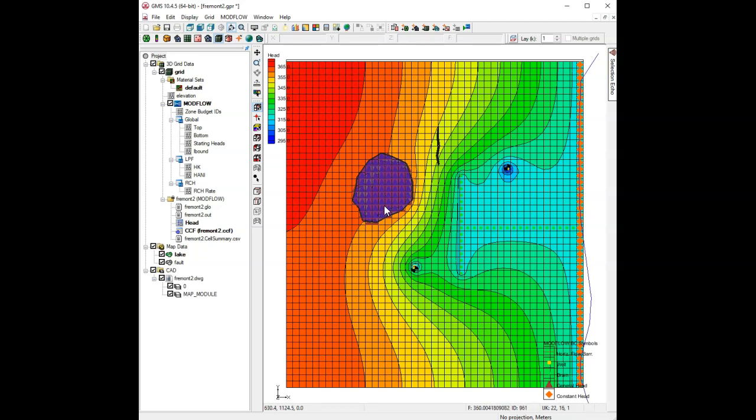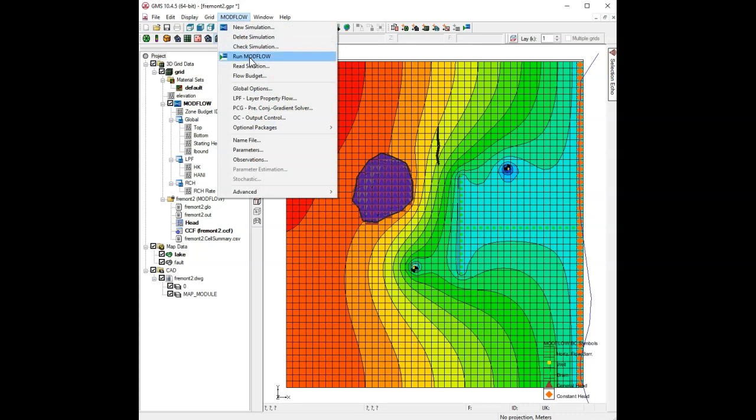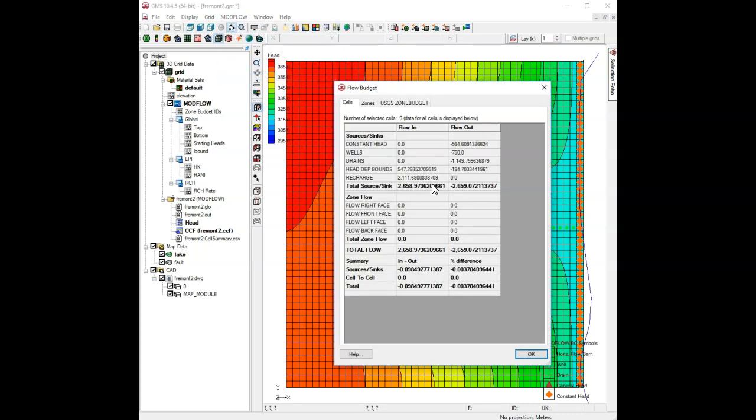A little bit of mounding in the groundwater occurs here, which is kind of what we would expect. And the water table under this, as I move my cursor around under this, it's pretty close to 360. So it's behaving kind of like a specified head boundary condition. It's close, but not exactly 360. And let's see how much water we're losing here.